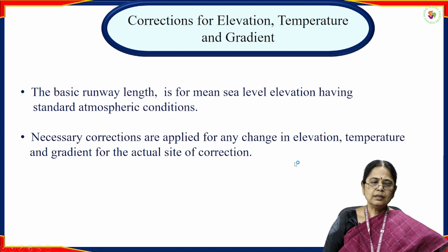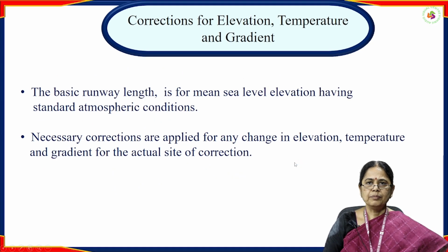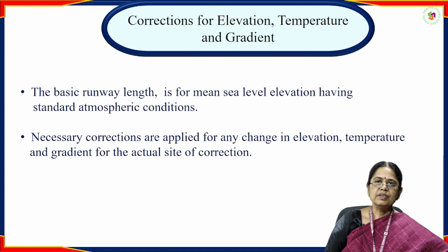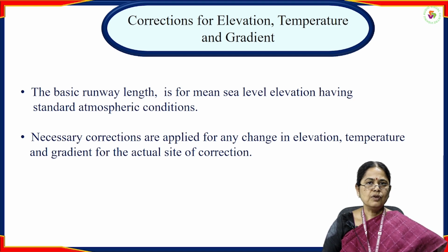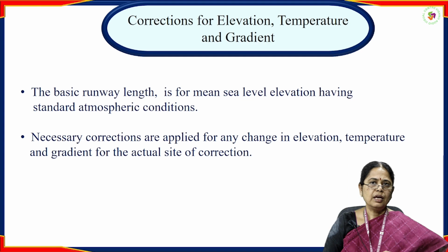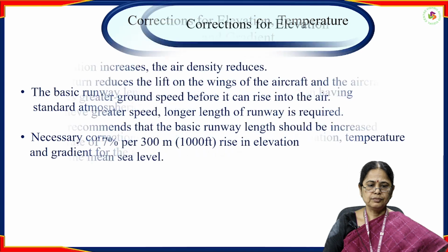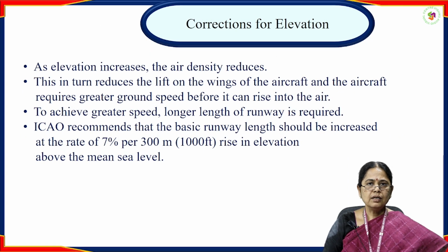So, the basic runway length is for mean sea level elevation having standard atmospheric conditions. It is necessary to apply corrections where there are changes in elevation, a rise in temperature, and gradient. First we see corrections for elevation.